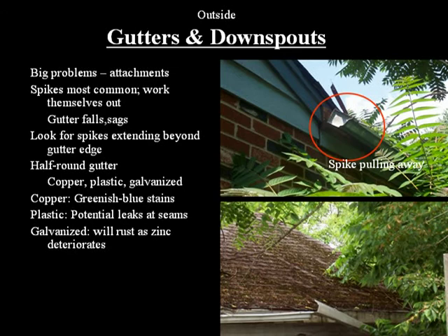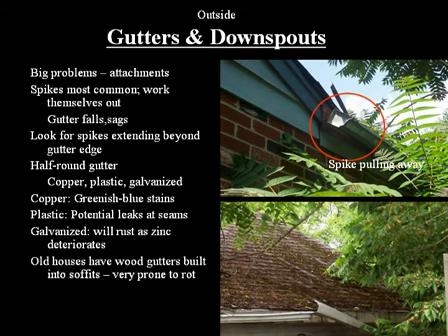Galvanized gutters start to rust when the zinc coating deteriorates. If you purchase an older house with wood gutters built into the soffits, these are very prone to rot unless the inside is lined with copper.